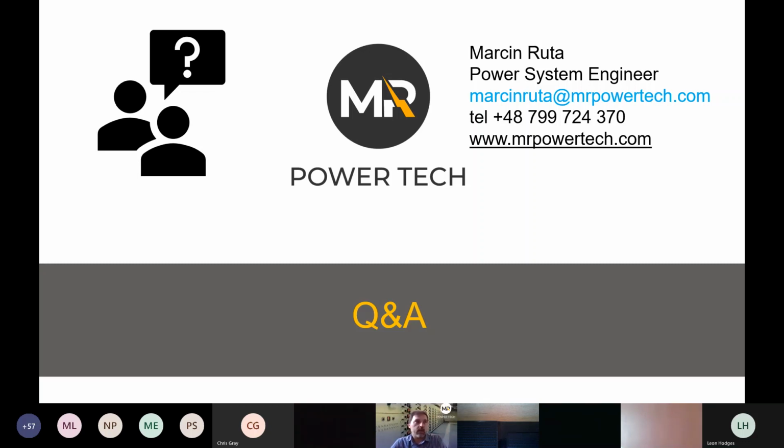You can use internal arc classified switchgears for it, for example. But there's always some area where you need to have PPE. You can use arc resistant equipment on low voltage switchgears also. But you can also use arc quenching or fiber optic arc detection to limit the energy. So usually this is the identification process which allows you to decide what to do next.